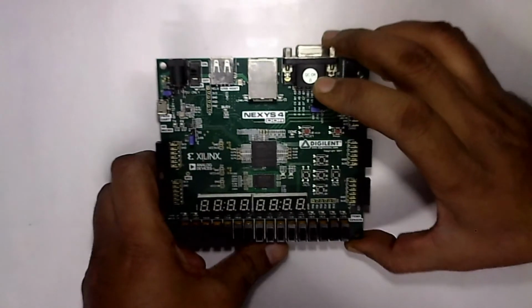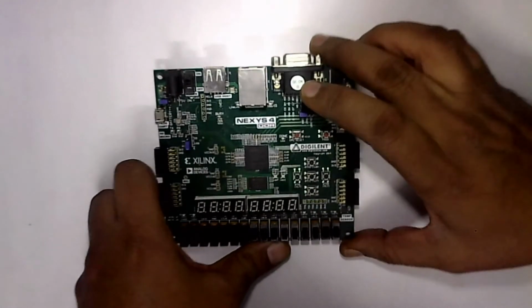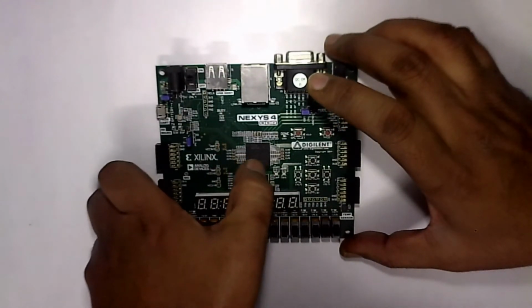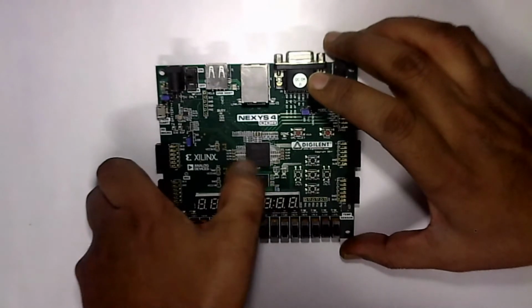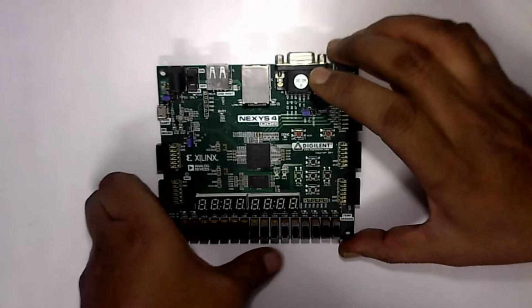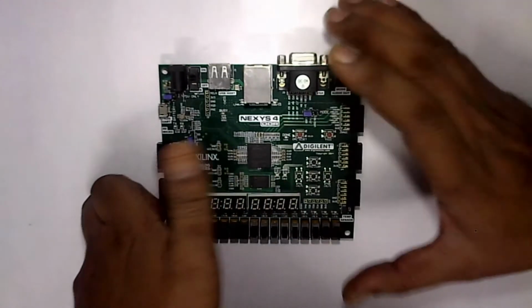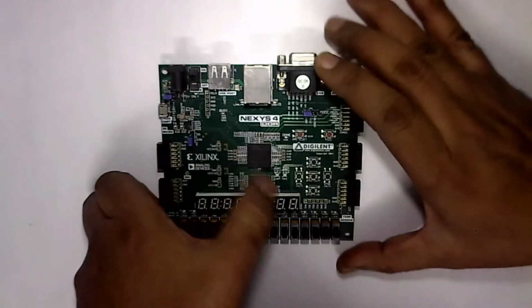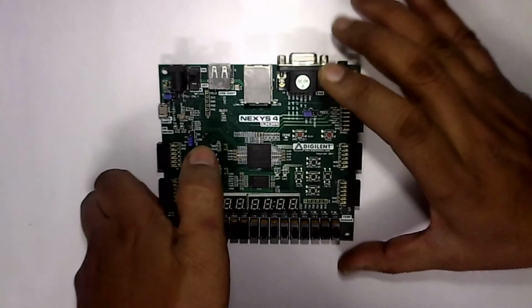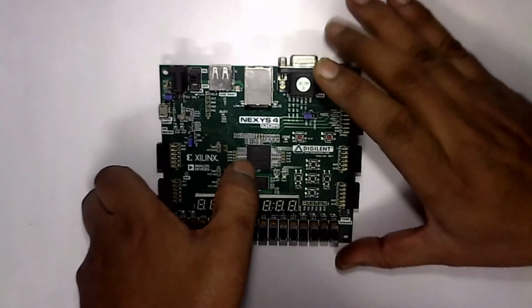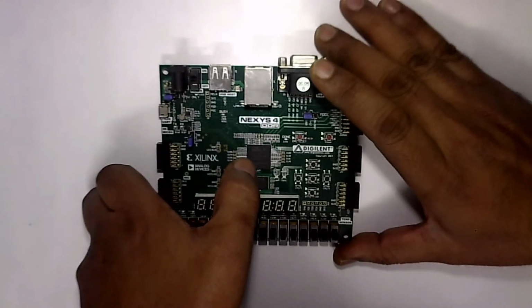Now there are other families of FPGA from Xilinx like Kintex, Virtex, so they are all 7 series. There is a basic difference which you should understand. Prior to these 7 series, which are all 28 nanometer CMOS process chips, the earlier ones were Spartan. Now Spartan series had a different kind of architecture, and that is now obsolete. Now 7 series is supported by Vivado, and earlier they used to have a tool called ISE.